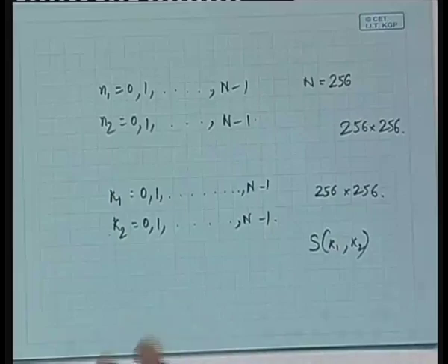Now, out of these 64,000 coefficients, if most of the coefficients do not carry energy, and only 10% of the coefficients in this array S k1 k2 carry 90% of the energy, in that case we should be preserving the 10% of the coefficients and discarding the 90% of the other coefficients, which carry only the remaining 10% of the energy.